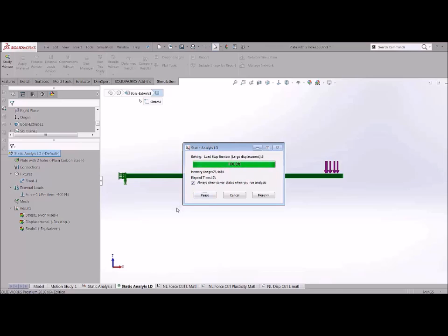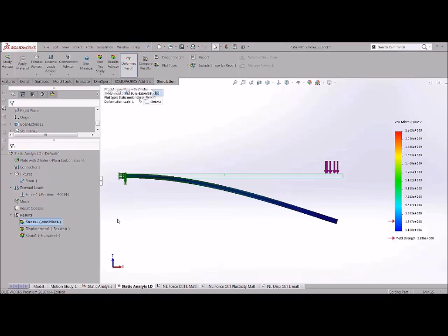In this case, it can be seen that with calculating the deformations at multiple intervals, the displacement plot is going to be more accurate as compared to just the static analysis. One thing that cannot be controlled is we cannot view the results in each of the intermediate steps, nor can we control how big each time step is taken.